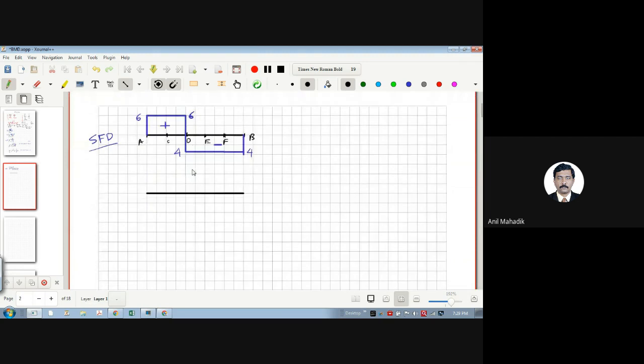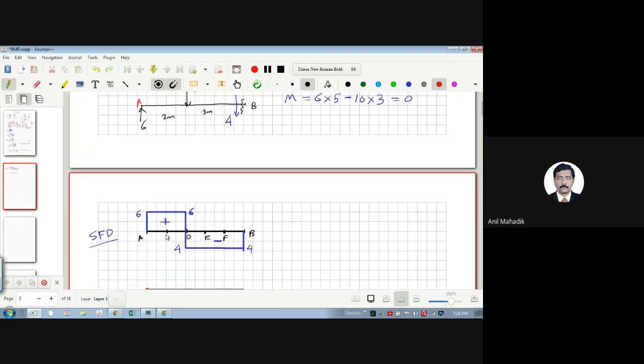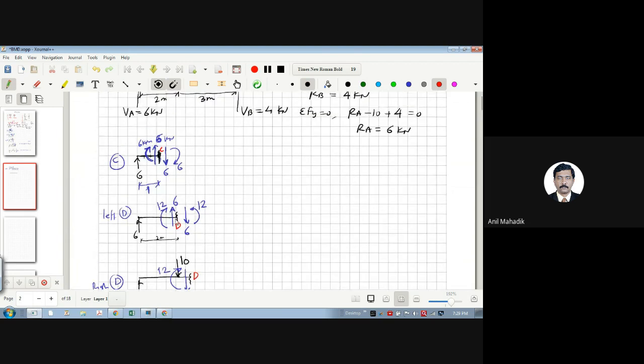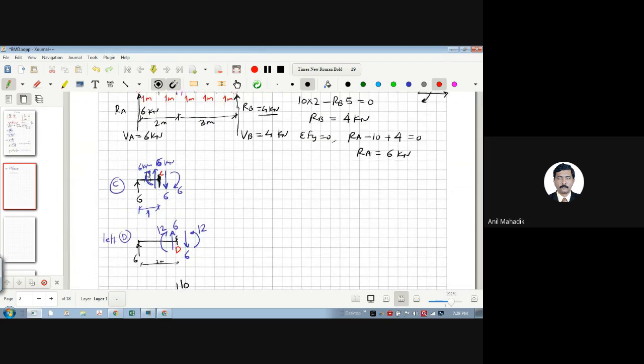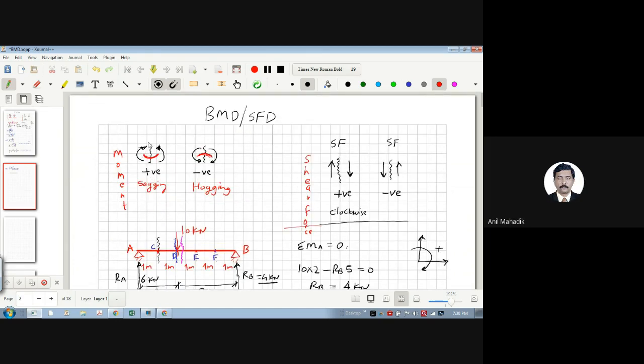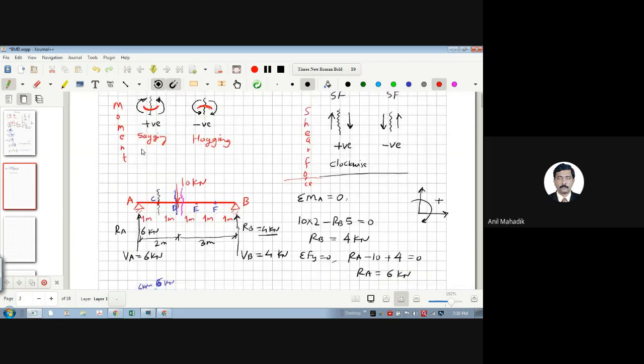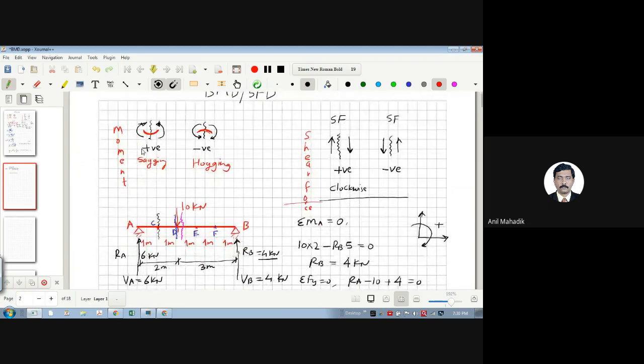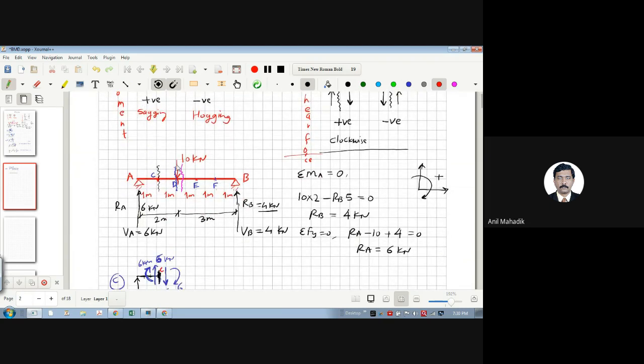अभी ये point है मेरा, समझो. What is the bending moment at A point? 0. 0, because it is hinge connection. So यहाँ ये तो 0 आएगा. Okay. Now what is the bending moment at C point? C point पे भी निकाला है ना हमने bending moment. कितना था वो? 6 kilonewton meter. Clockwise मतलब left side को clockwise. ये क्या है? Positive. Yeah. So positive. Now if this point load is there on this beam, how will it bend? Bend कैसे होगा ये beam?